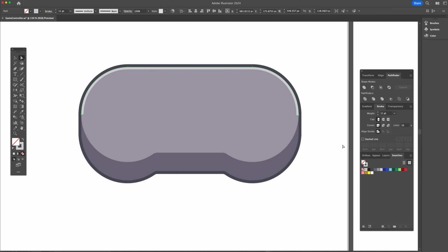All right, so currently this is behind my large path, my large dark outline. I'm going to bring it in front, so Command and right bracket. Now that's a little bit thicker than I want it to be. That's okay. I'm going to want this path to be entirely on the inside, the stroke to be on the inside of my path. So you'll notice that I can't use my align stroke to do that. That's because this is an open path.